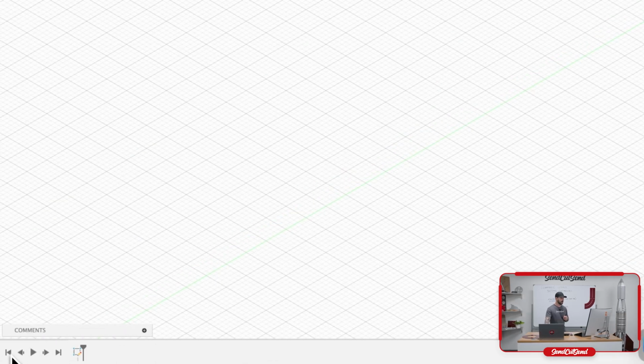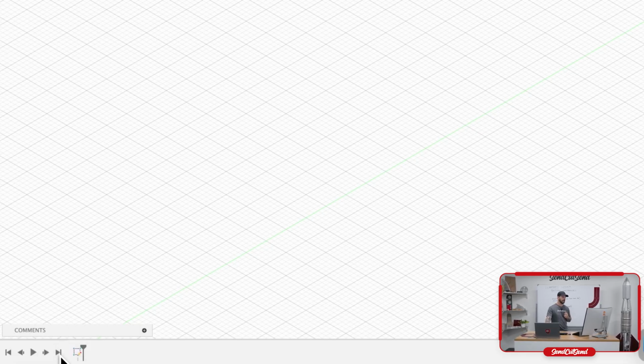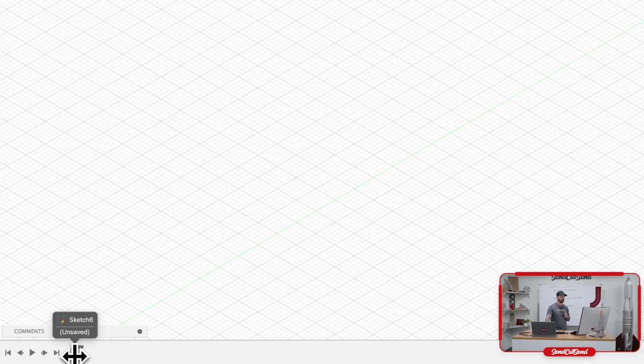You can click right here on this rewind button, and you can see options like move to previous step, move to the beginning, or move to the end pop up. That can essentially create that sketch or rewind past that sketch. If I move this marker, I can also click and drag and move over here. I can click and move it in front of that sketch.